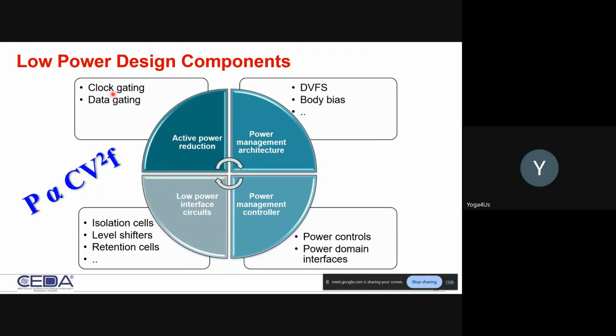Makes sense. Well, that's what I'm thinking. Basically, data gating with a recirculation mux or something like that, you kind of block it, right? But not at the... makes sense. Yeah. But then they will help the system level power aspects. I agree. Yes, dynamic power aspects. Yes, correctly. Thank you.